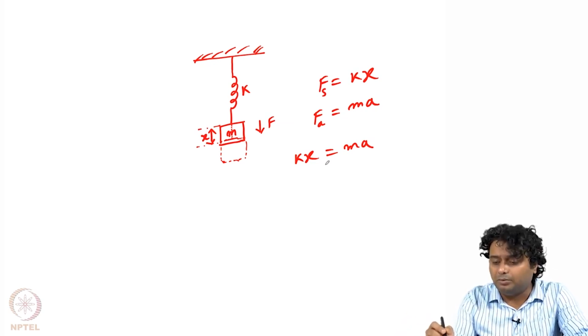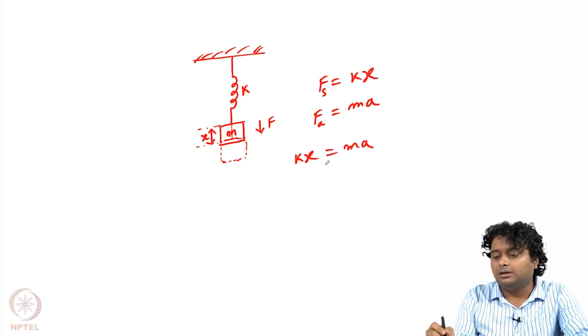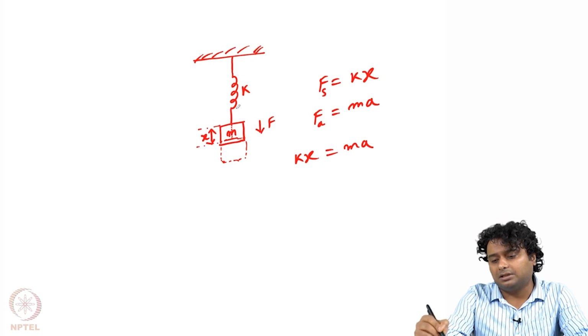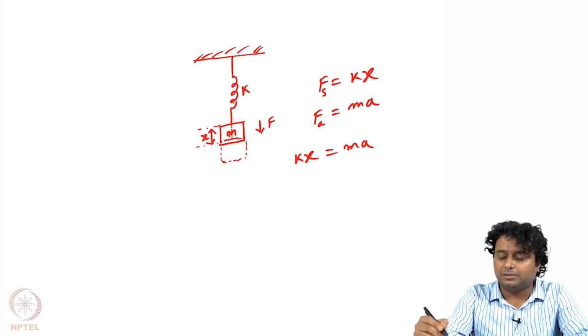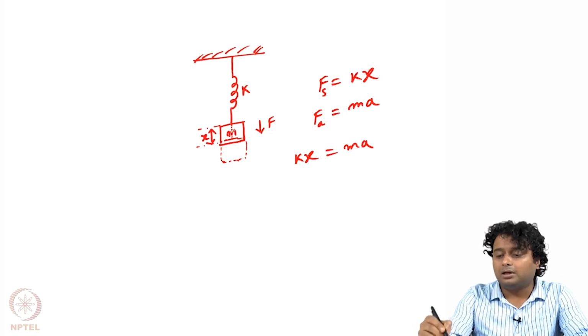Actually the accelerometer or acceleration sensor uses this principle. So now assume that this is our sensor, this spring is our sensing structure, and it has the sensing element, etc. Okay, and some force is applied on this mass, or this mass is suddenly accelerated, and that we will measure with this sensor.